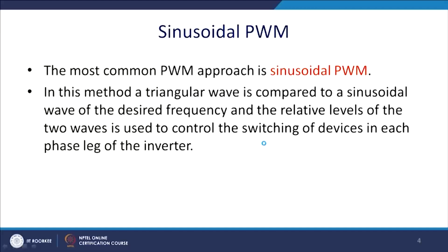Now, as told in the previous case, the most common approach is sinusoidal PWM. Here the sine wave, which is the control or modulating wave, is compared with the triangle wave, and accordingly the reference will be generated. We can see this in the next slide.